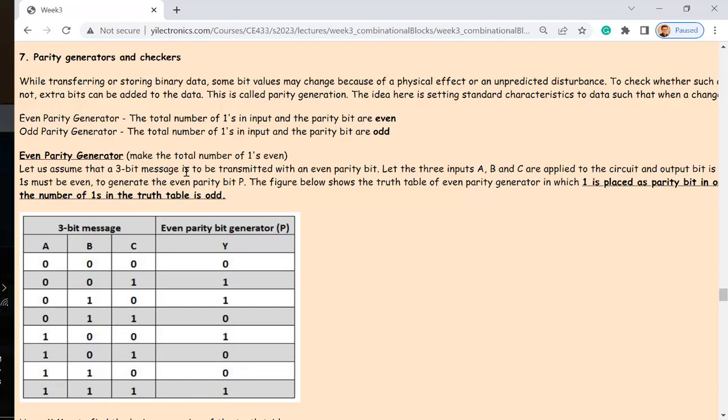No? It's just creating one extra bit. It's not data, but it's just trying to make up an even number of ones. If I have an even number of ones already, there is a digital circuit that can detect that. For example, I already know that I have an even number of ones from the temperature sensor's data. Then I'm not going to add a 1 to the parity bit because it's already an even number. Just send it over, so the checker is going to check: do you have an even number of ones? Yes. Good.